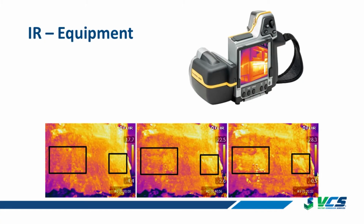This is kind of an IR camera here, and this is kind of an example of a time lapse on a dam face, which can be a wall of concrete anywhere. And I've highlighted kind of two areas. And in the morning sun, they just kind of look like any other area. But as you see, as the day goes, you get this hot spot right there and right there. And so clearly there's a delamination occurring. You can see that delamination as the sun warms that face.